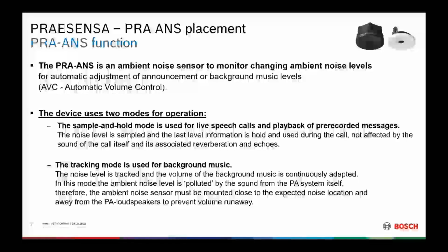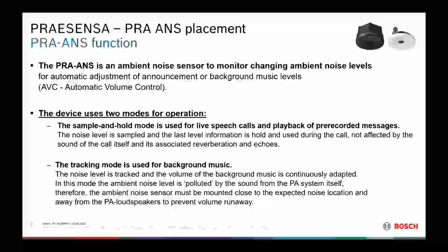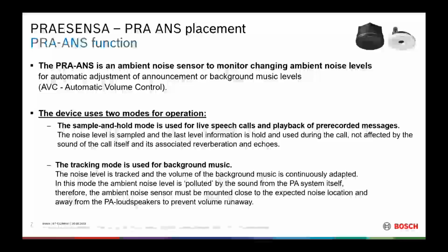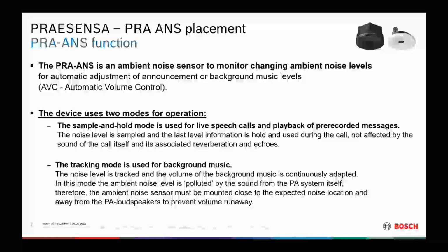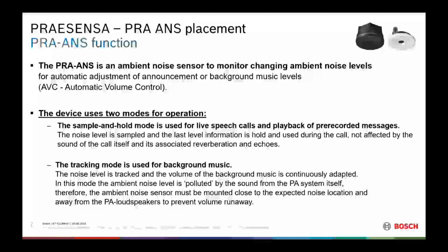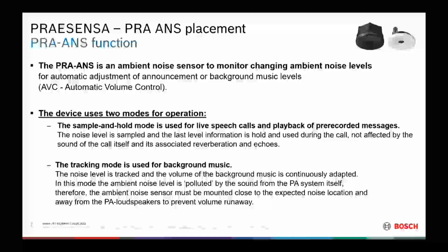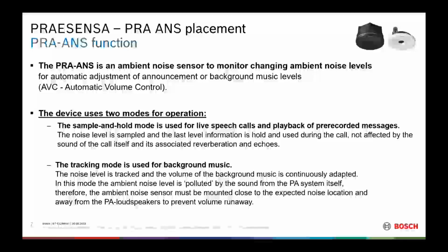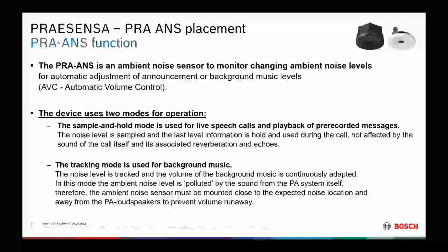Finally, the device uses two different modes for its operation. One thing is quite simple. It's called sample and hold mode, and we can use this normally for a live speech, for a live announcement, or when we want to broadcast pre-recorded messages. And so in those cases, the noise level is continuously detected, it is sampled,